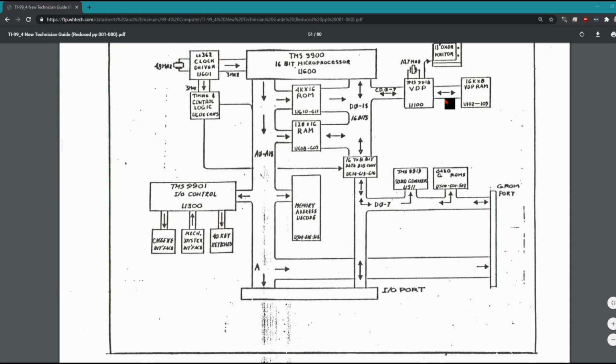That's the chip I've already changed. This has an 8-bit data bus, and the video display processor is also connected to the data bus just with the first 8 bits. And then down here is a 16 to 8-bit interface, which converts the wide 16-bit bus just down to 8 bits to run things like the sound generator and the additional ROMs to boot the computer. It's the expansion port connector for the cartridge, that is.